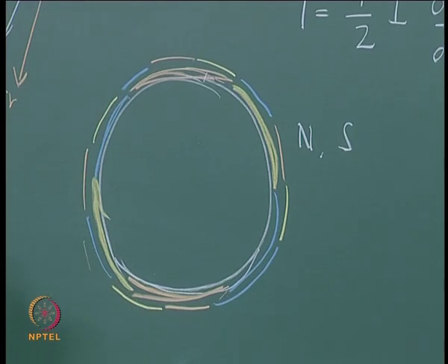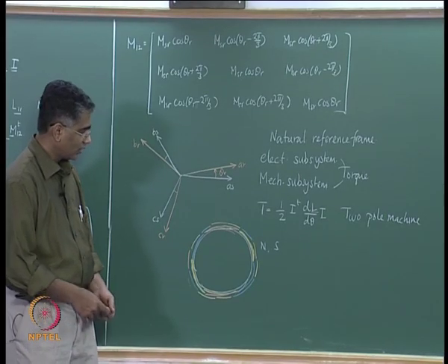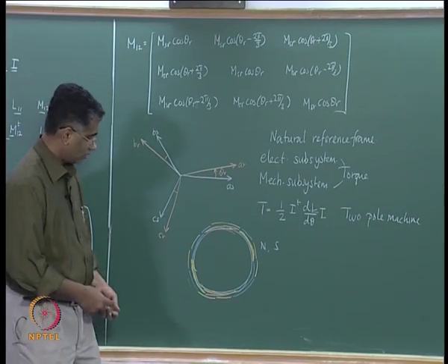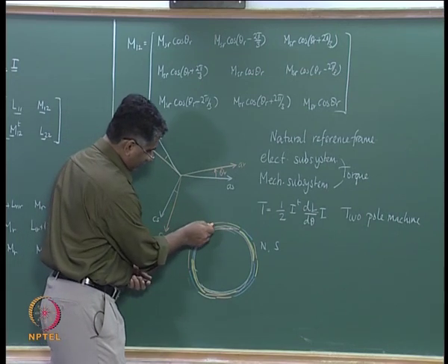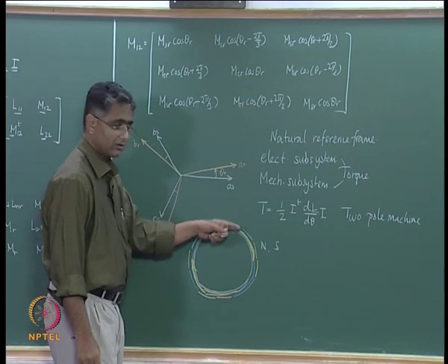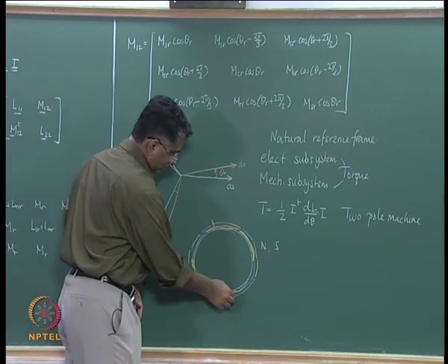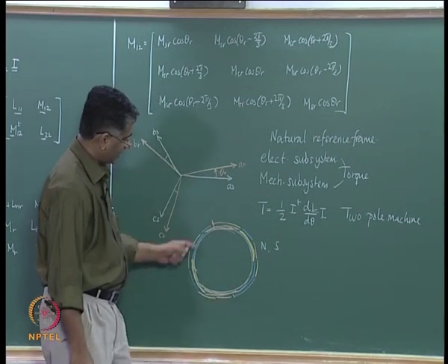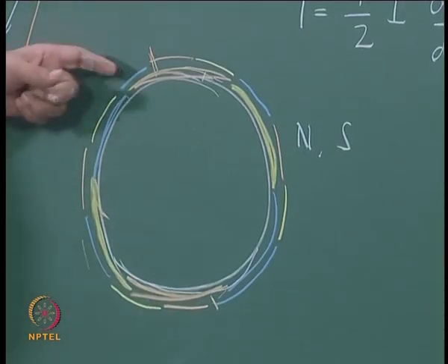So, the stator has to be rewound or redesigned if you want more number of stator poles. However, we know that whatever is going to happen between the start of one cycle of the MMF waveform and the end of one cycle of the MMF waveform, the same thing is going to happen this side also.